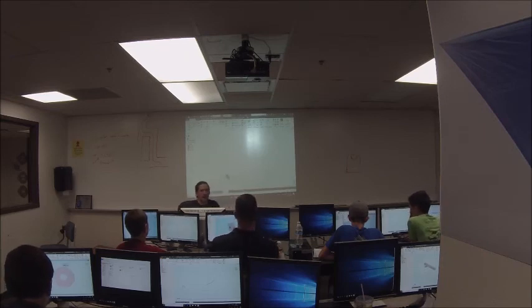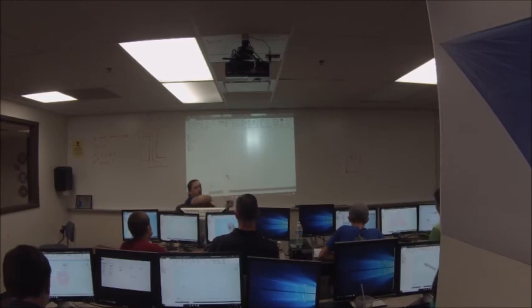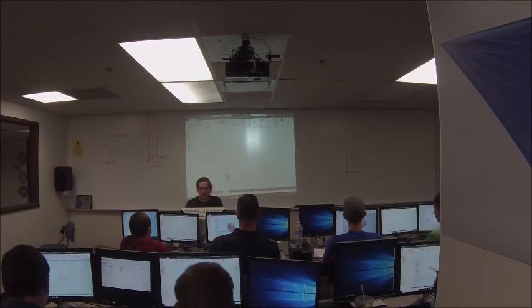So what we're going to talk about now is the Revolve Tool. And the Revolve Tool does pretty much what you would expect it to do. It takes a shape and it revolves it around. Instead of stretching it this way, it stretches it in a circular fashion. And that's useful for making round parts, obviously. You don't have to extrude a full circle. You can extrude 90 degrees or whatever, any angle you want if for some reason you need to.